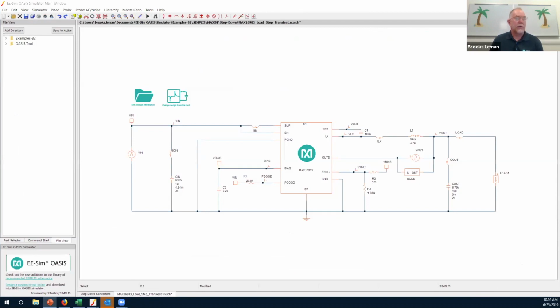The other big advantage to SIMPLIS is the Bode plots are effectively built in. You solve the AC analysis directly from a POP time domain simulation, which is really effective for topologies that are difficult to analyze with average linearized small signal modeling. You can get Bode plots for loop gain and phase.